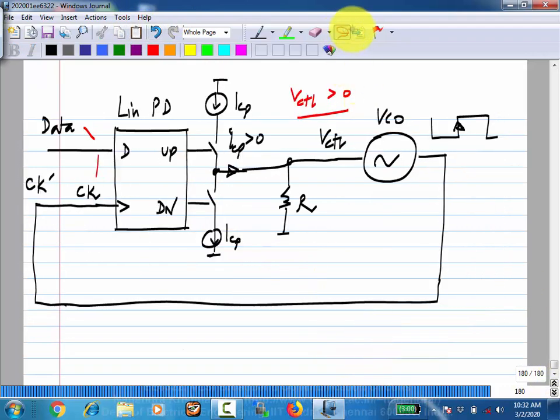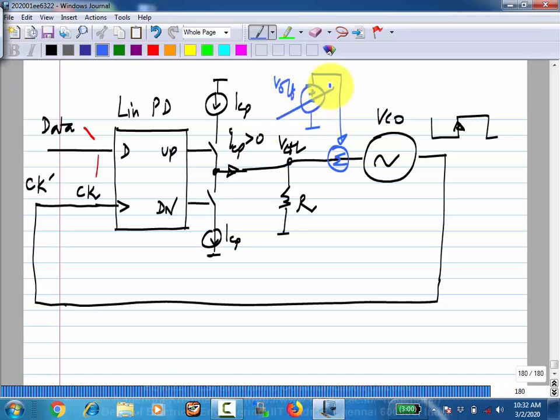So this by itself works only when the free running frequency matches the transmit frequency. So what I will do, my new introduction, is that I'll add V offset and I keep on varying it until the free running frequency becomes exactly equal to the transmit frequency.